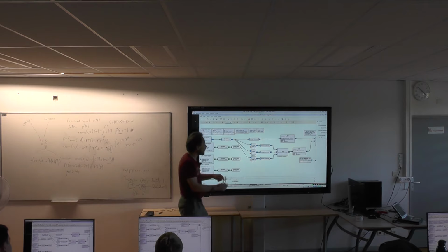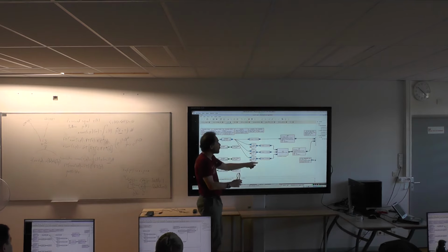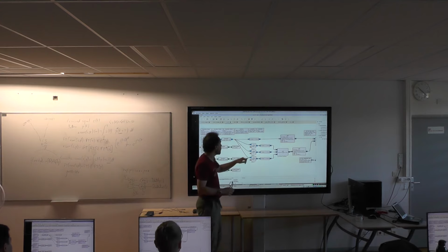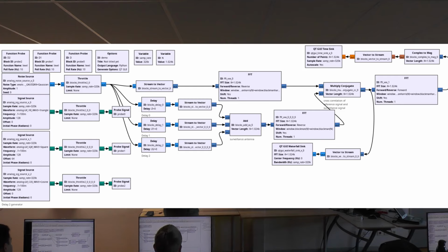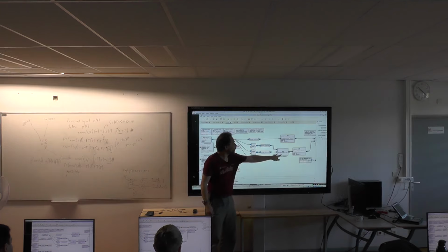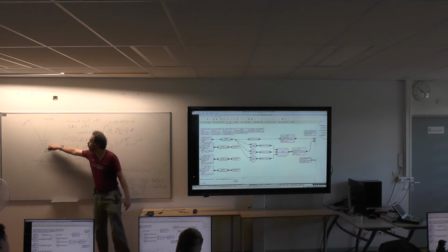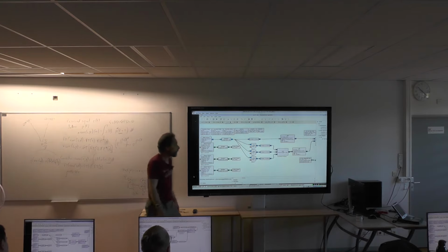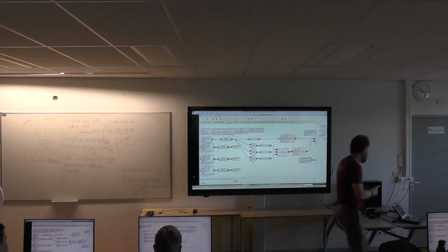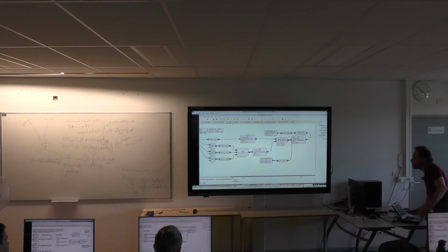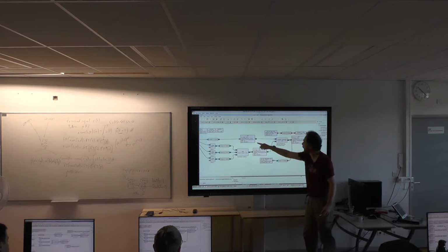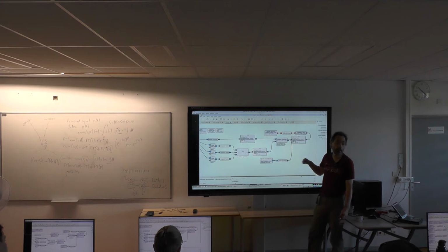So what I'm going to do is I have three targets, and these three targets will have a time delay shaped as a triangle, as a square, or as a sine wave. And yet, even though I have three targets backscattering the information, you see that the receiving antenna, the surveillance antenna, only receives the sum of the voltages of all the oncoming signals. And when you want to detect all the targets, you only take a single Fourier transform on your surveillance antenna. You take the Fourier transform of a reference antenna, multiply, conjugate, and go back to the time domain.